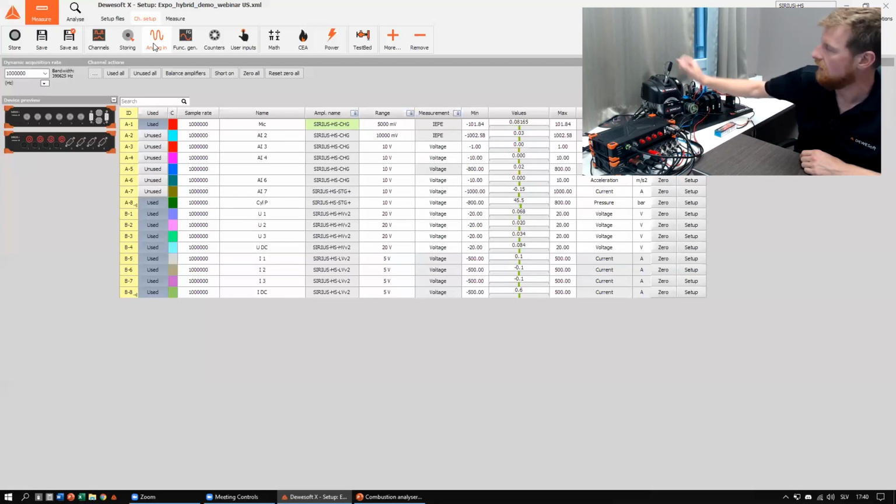So here we have just a voltage type pressure sensor. But this slice is a charge type input. So also charge type sensors could be directly connected to any one of these inputs. On the bottom, we have also one high-speed slice, which we call a power slice. So it has 4 high voltage inputs that go up to 1,600 volts directly.